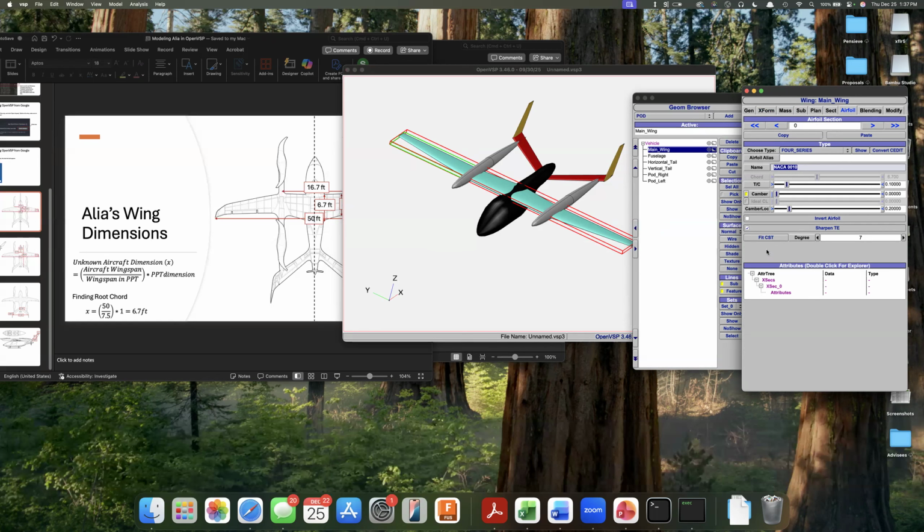You may need to learn a little bit about basic airfoil aerodynamics, but when you play around with different series of airfoils, you will get drastically different performance metrics because the aerodynamics of an aircraft is very, very, very sensitive to airfoils. All right. So even a 2% change in thickness of the airfoil can have drastic effects in the overall performance of the aircraft.